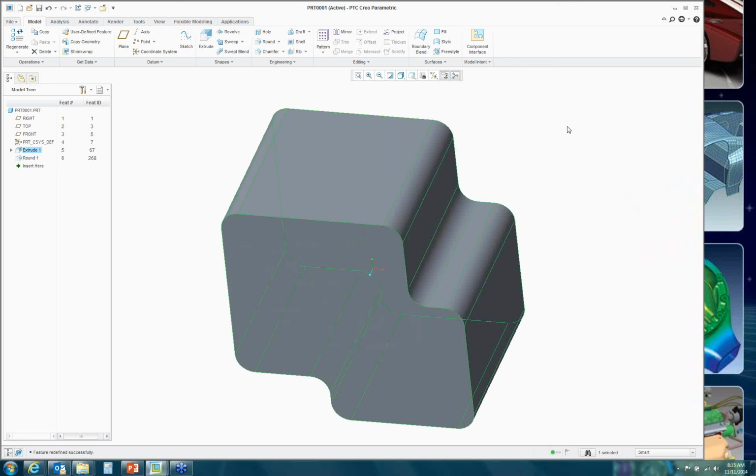And it's a very powerful tool because it helps our models from failing due to missing references. Because that intent selection is really a collector, but it also has an ID associated to it. Okay? But that ID will never change because it's not associated to any physical geometry.